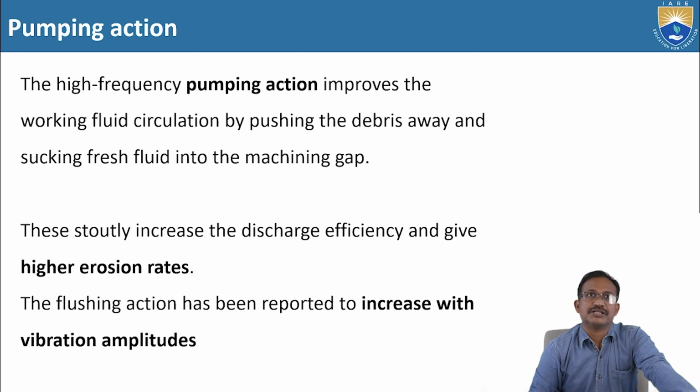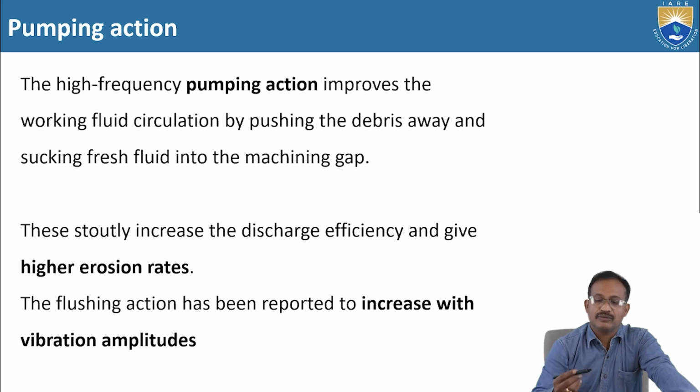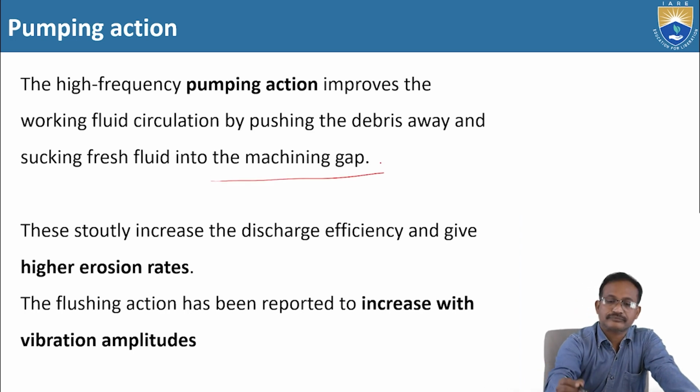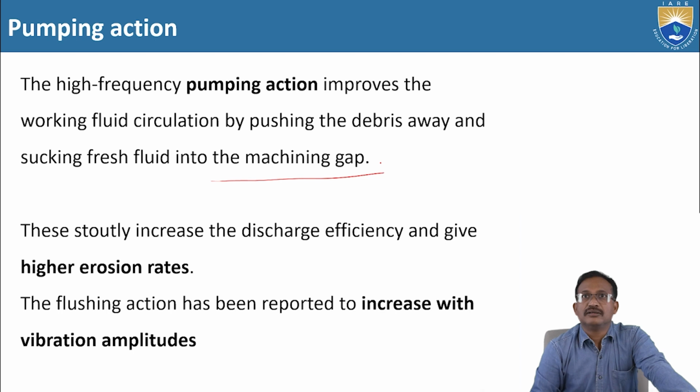The high frequency pumping action improves the working fluid circulation by pushing the debris away and sucking fresh fluid into the machining gap. See here, usually we have a gap between the tool and the workpiece. That is nothing but the machining gap.